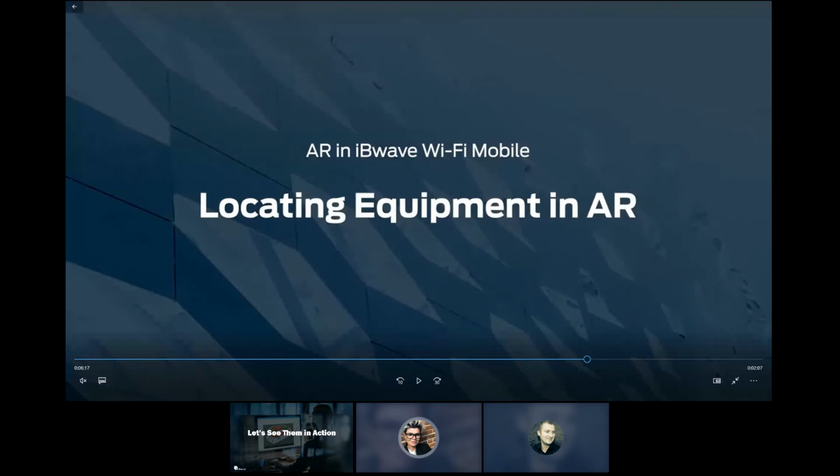Jamal, just one follow-up question to the height configuration. Just to confirm, the height can be adjusted without rebuilding the file, correct? Yes, you need to rerun the heat map, though. You need to rerun the prediction because the calculation has to be made again for the new height. Yeah. That's the only difference.